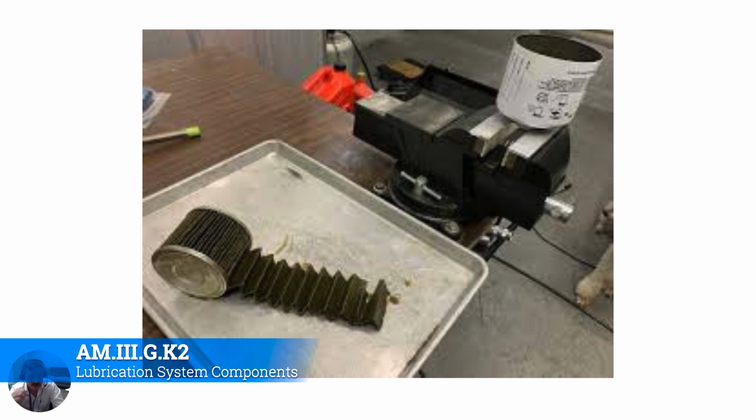He's laid it out in a pan. A good thing to do is take a flashlight and go down the sides and see if you see anything glinting. If you see something glinting, that's going to be shards of metal, and that's something the owner needs to know about. Once you have found metal, you'll go to the maintenance manual and do follow-on maintenance to try to figure out where that metal is coming from and fix it.